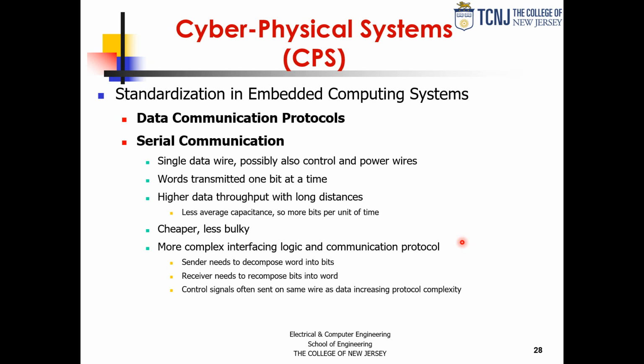You need to know that these things exist. These days they are integrated in high performance systems like high performance FPGAs. If you go to Xilinx and you're going to use this technique of serialization, you can pick an FPGA that has a SERDES integrated in it, because it's actually a very sophisticated piece of analog circuitry. Even though the signal is digital, since it's at such high speed, it's treated as an analog signal.